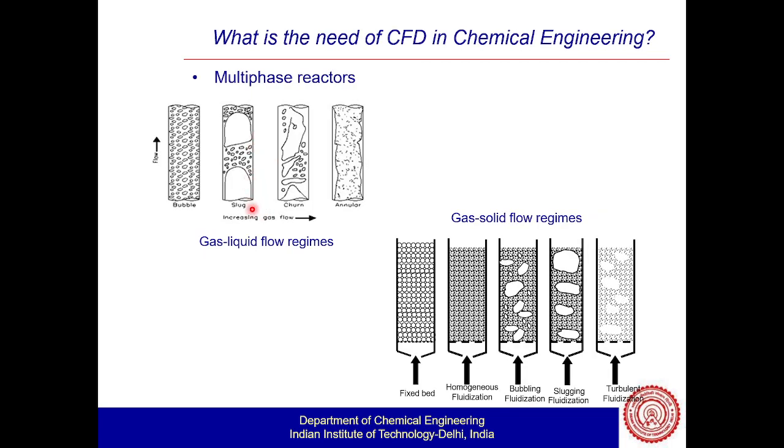So going to the multiphase reactor, here you can see a bubble column. It's filled with a liquid and then we are putting gas inside, which causes these multiple bubbles to form, which have this meandering motion and go to the top of the column. So it's difficult, or not possible, to get these accurately represented by the MFR or PFR models.